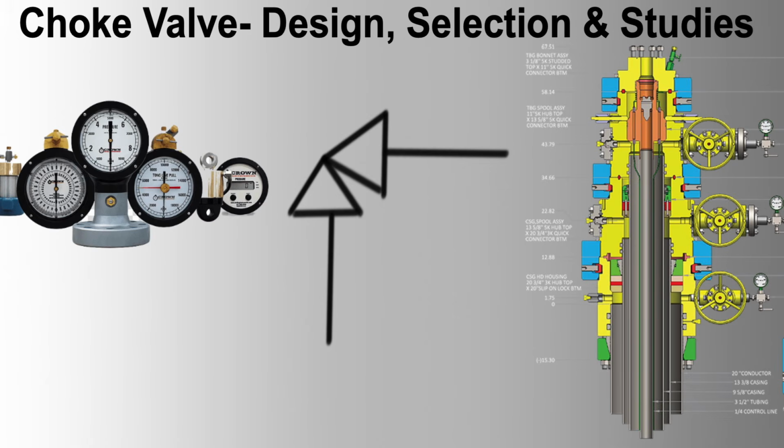Problem: corrosion of valve components in H2S environments leading to failure. Solution: use corrosion-resistant materials, such as Inconel or Hastelloy, and ensure compliance with NACE MR0175 / ISO 15156 standards.